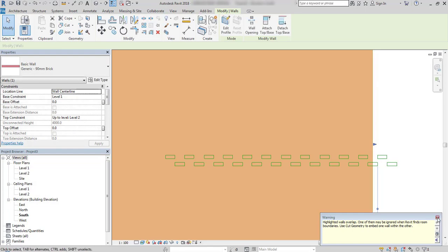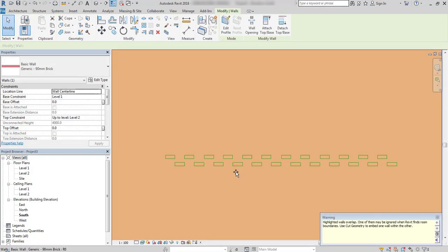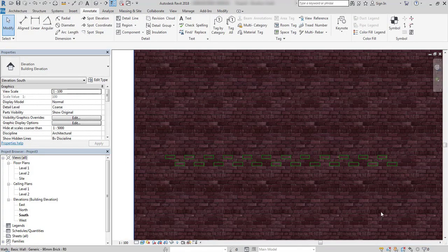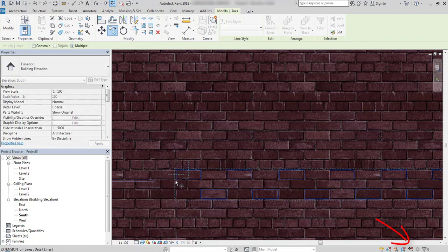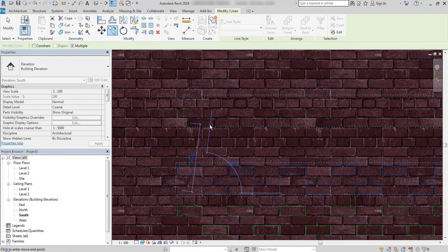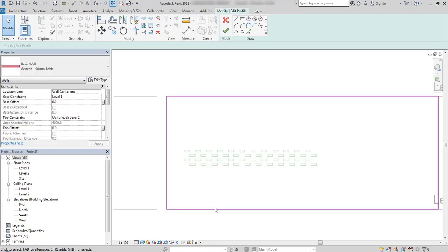By mistake I dragged this wall also, and you see this error. We can cope with that by deactivating the drag and drop option from selection options. So now I can use the selection with frame command to select and copy these rectangles above.